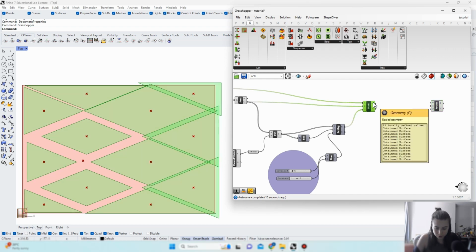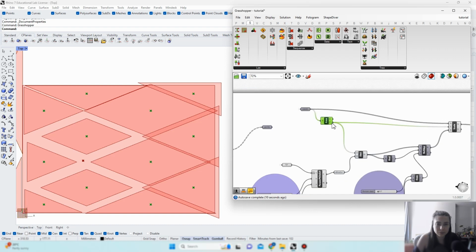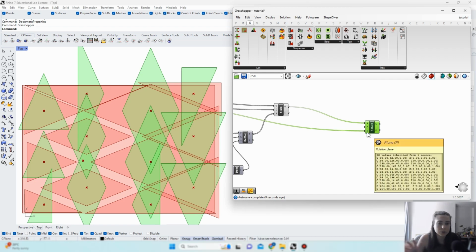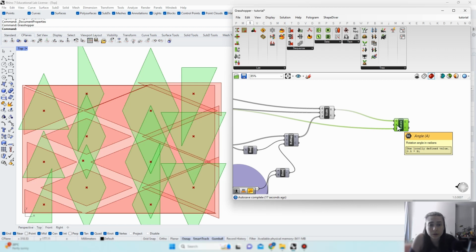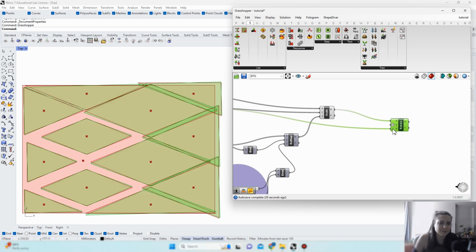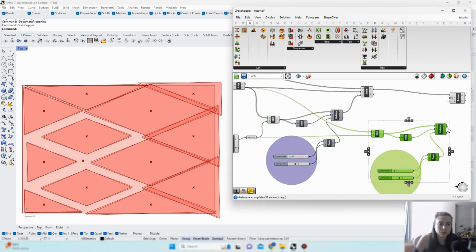Now we take this geometry and we need to rotate it. Of course, as planes, we need the same thing. It automatically creates an XY plane, which is good enough for us since we are 2D here. It creates XY planes in these points that we just feed it, which are centroids. All right, now we need the angles. It's literally the same thing as factors, it just operates differently. What I do is put degrees because it's so much easier. And we need to do literally the same thing. We need to remap. Actually, you can just copy this.